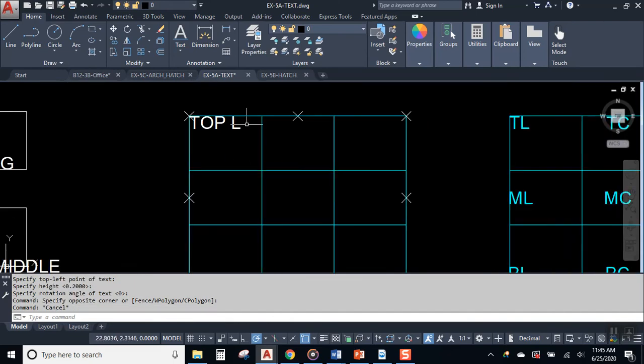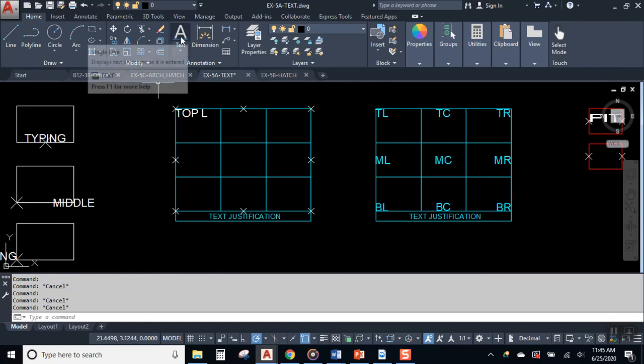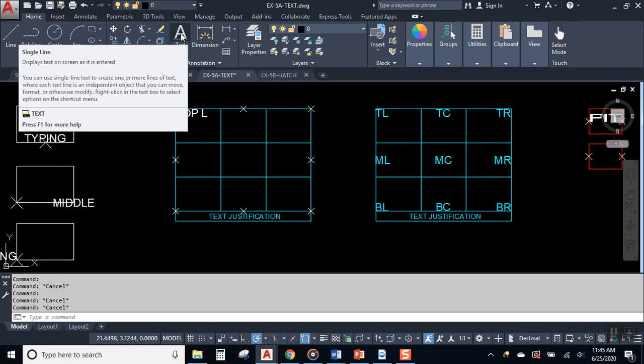Now, you don't really have to go through all of these boxes if you understand this concept that justification lets you place the text exactly where you want and gives you a grip to move it later on. One thing that might be helpful, though, is to take a look at the middle center justification, because this is a kicker and you want to be able to do this. So let's try it together.